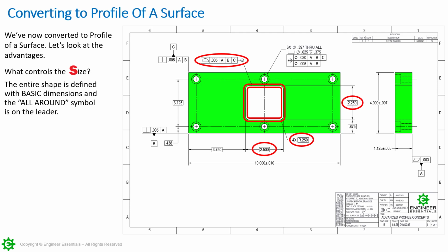The design is going to require that. But according to the way that it is right now, any given element on the surface could either move in or out by 2.5 thousandths, a total of 5 thousandths. Oftentimes we do treat profile tolerancing like plus or minus, because we have an exact location where it's supposed to be, and then from there it can deviate half of the tolerance in, half of the tolerance out.